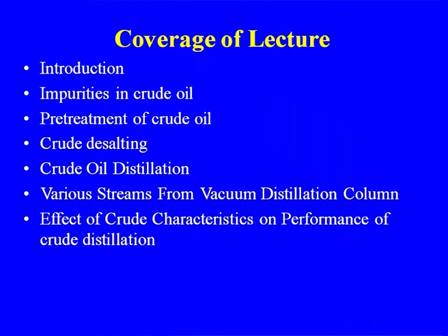So, impurities and their pre-treatment removal is very important, and some of these pre-treatment steps, whether at the site or at the refinery, will be discussed here, along with the crude oil desalting process. There has been a lot of development in crude oil desalting, but normally, just to meet the requirement of the process, we are having 2-stage crude oil desalting.